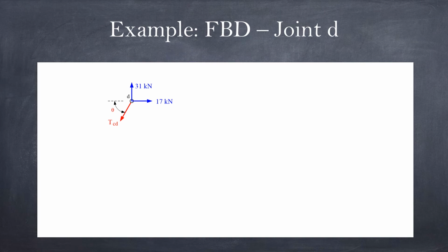As I already said, because we don't know h, we don't have the total complete picture of the triangle. So the angle theta that we need to actually take components of TCD is unknown. So these are two unknowns: one is the tension force in the CD cable, and the other is the angle it made to, in this case, I draw it as the minus x direction, theta.